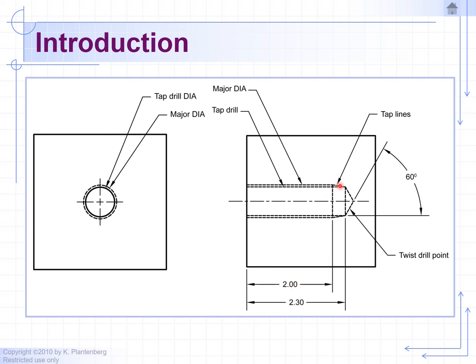And then you go beyond, and this is where it starts tapering. And then we have this V shape due to the drill. So for the tap that goes in here, first you'll drill a small diameter hole, and then you come in and tap it. So this represents the end of the drill, which has a conic shape. It's just easier to scoop material by having a conic end here on the drill.